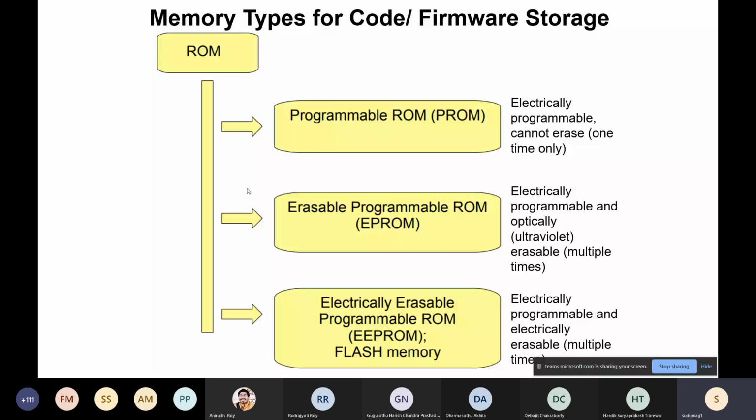So EEPROM typically stores the data that will come to it again and again. If you store it in RAM, it will forget, obviously. But if you store some user data which you will access again and again every time you turn on the drone or whatever, then the EEPROM is the preferred memory location where you can update it many times.